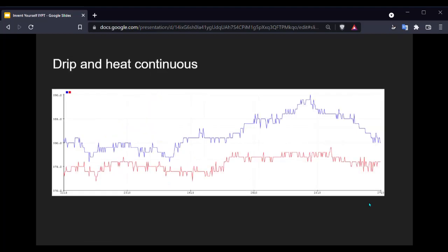This graph displays the two thermistors while the flow and heat are constant. The difference between the two thermistors remains generally the same, and even despite this fluctuation, it is clear which thermistor displays the higher temperature over time, indicating the direction of flow.